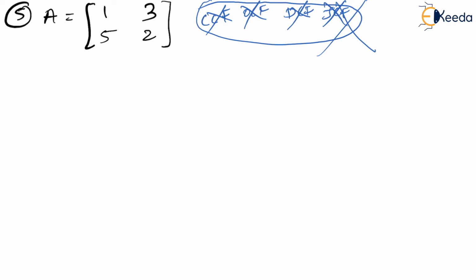So now you will understand the advantage of having the system in the four standard canonical forms. The advantage was that we were able to check the stability very easily. Even if it is CCF or OCF, we were able to find the characteristic equation in a very easy way. Whereas in the case of diagonal canonical form or Jordan canonical form, just by observing A, we could say whether it is a stable or an unstable system.